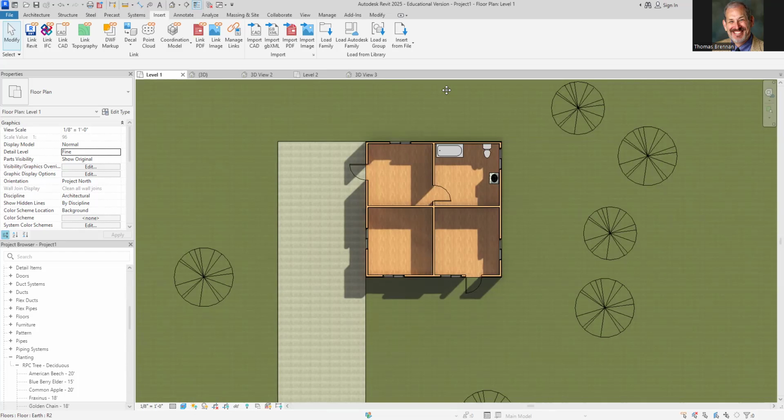What happens is if you click on this invert up here, click on it once, click it again one more time. There you go. And so you want to go on the Architecture tab, and you go to your floor here. Choose floor, and you want to change the slab. Twelve-inch filled concrete, that's what you want.